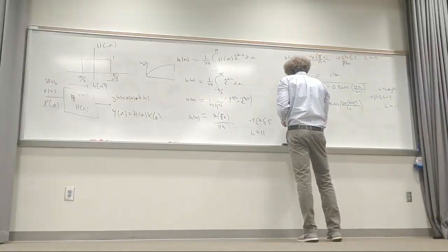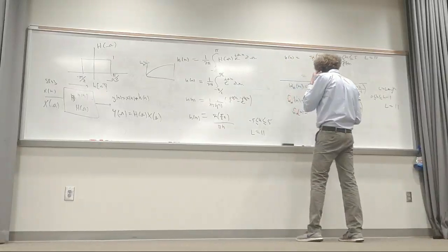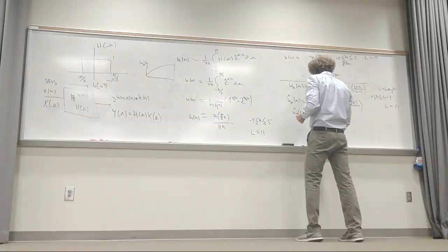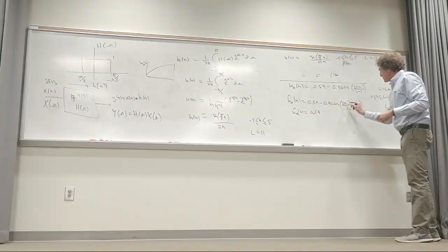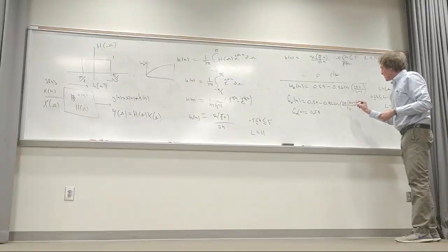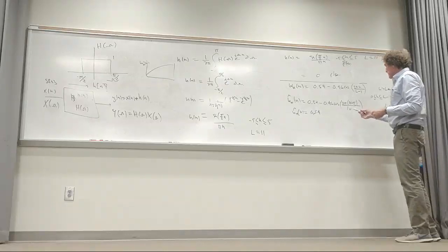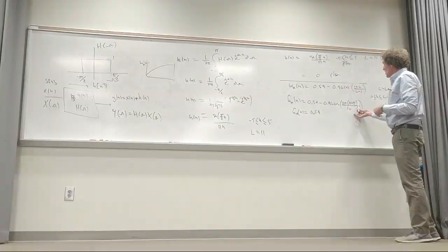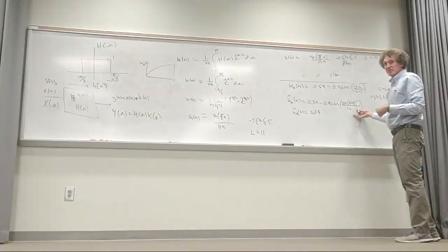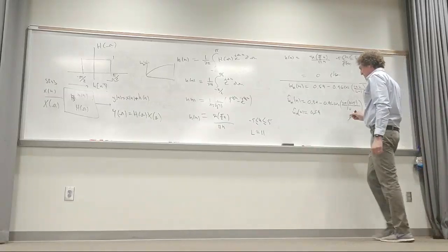But there's a nice little thing that happens when you do this. So this Hamming window, it's actually got the hat on it because it's adjusted, is 0.54 here, but I want you to notice what happens here. This is 2 pi n over 10, right? So that's really pi over 5 n, right? But then you've got 2 pi times 5 over 10, or 10 pi over 10, or simply plus pi, don't you? Let me go ahead and write this.